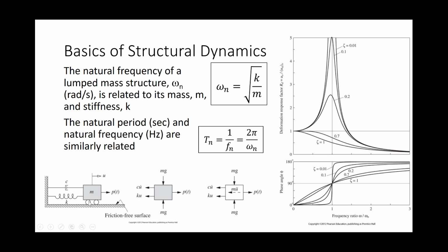You're measuring displacement of that mass, and that forcing is resisted by 2 things. It's resisted by the damping of the structure that's related to the velocity that the structure might move through. It's also related to the stiffness of the structure, and that is, if the position is changed, there's a resulting force that attempts to restore the structure to its equilibrium condition.